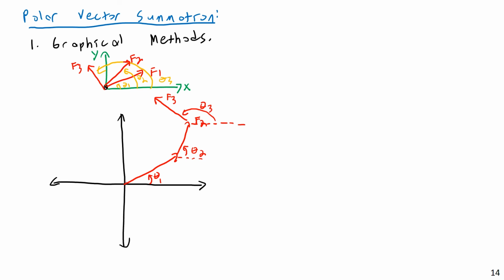And the net force on this object would literally be, if you're doing this via graphical methods, really all you have to do is nothing more. If you plot these all by hand, if you plot them precisely, if you use an actual ruler to measure out a proportional distance, if you use a protractor to measure out a relatively precise angle, you can literally just take a straight edge and strike a line from the original origin right to F3.